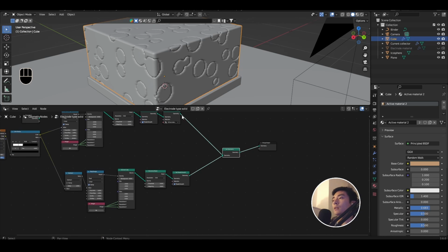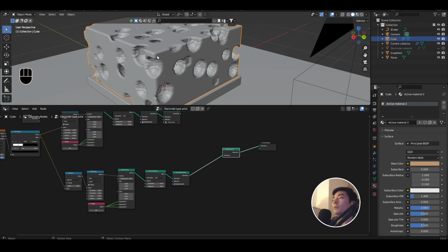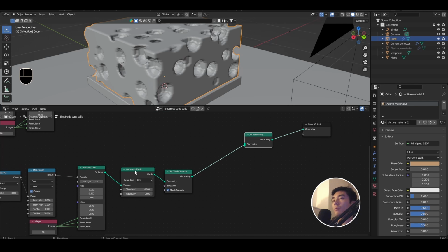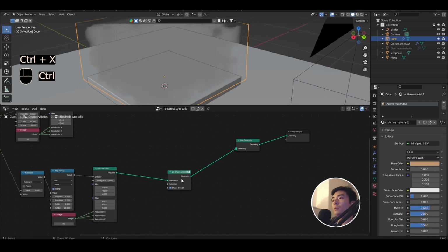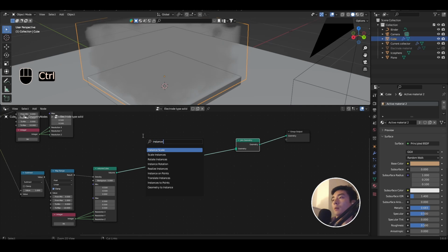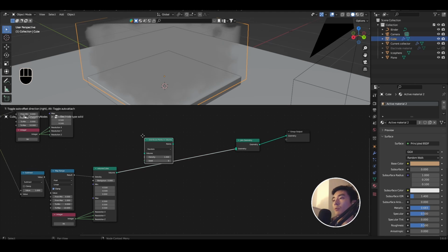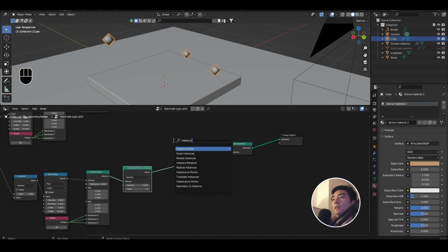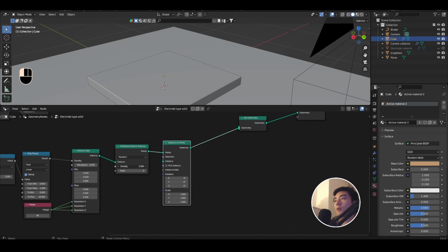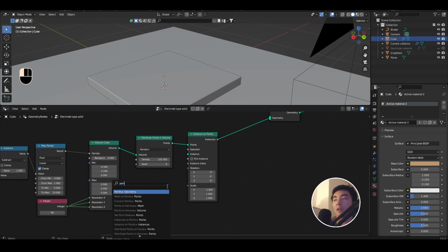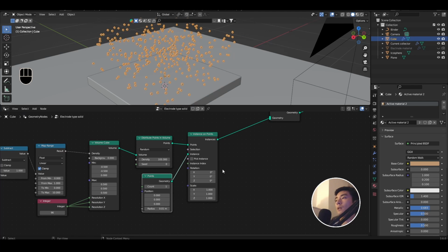What we now want to do is use this surrounding volume to instance further points. So here, rather than using a volume to mesh node, I'm going to delete these two things, and we're going to use this volume to instance a bunch of points. So distribute points in volume. And again, we want to add an instance on points node. Let's crank up the density and plug in points with a radius of say 0.01 into the instance socket.